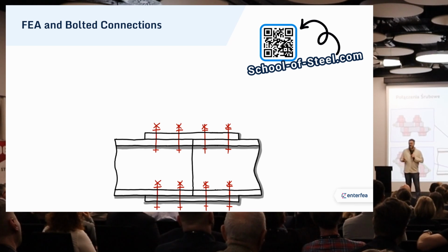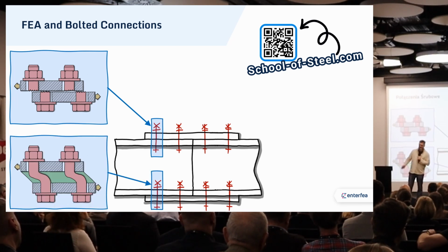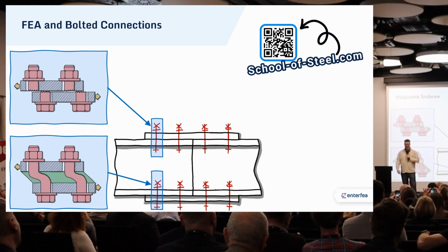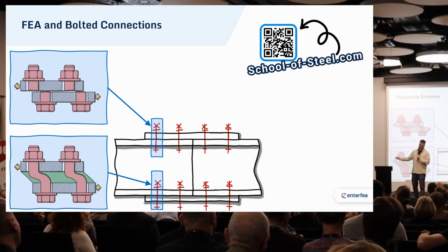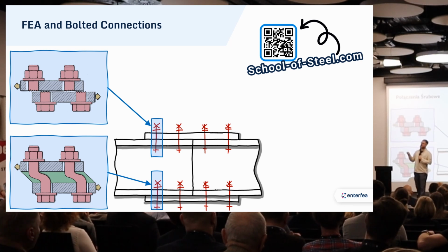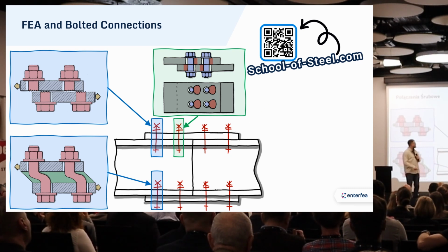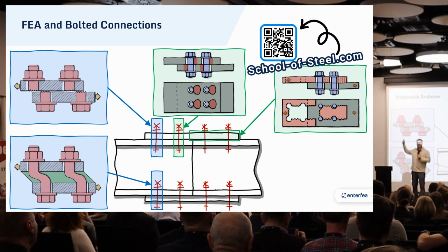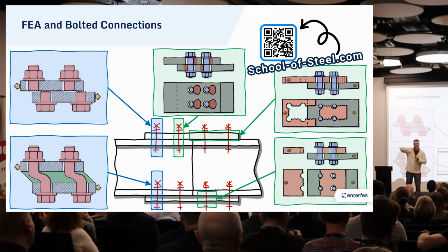The bigger problem will be when you have connections in shear, like this one here. Bolts in such connections can fail in shear and sometimes in bending, although in reality, bending of the bolts, if the plates touch one another, is usually omitted in design. It would actually happen if you would have an actual air gap or maybe some sort of non-constructional material between the plates, like a seal of some sort. Then it would be a bigger issue. Then you have the bearing contact stress, contact capacity of the plate, block failure of your plates, and also the failure of the cross-section weakened by openings.